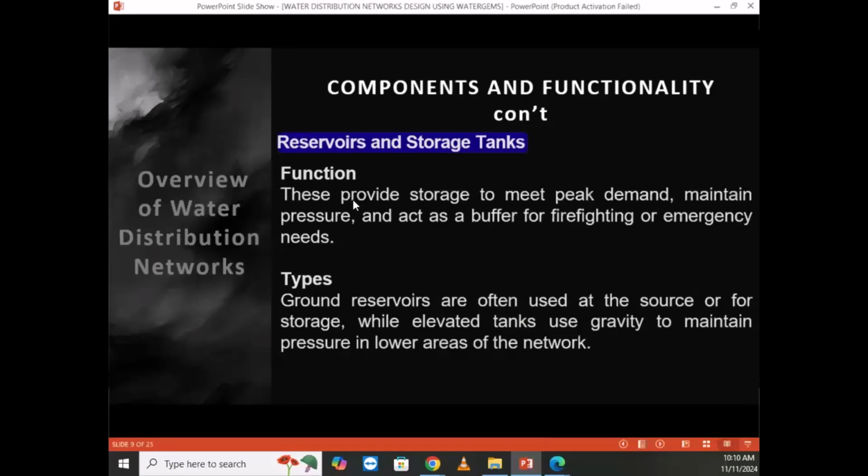So this also helps to meet the peak demand. All of us in the morning, people are consuming much water. If people are consuming much water in the morning, you have to size your tank so that in the morning the tank will be full, people will consume the water, and during the times of 10, 11, the water will be filling your tank. So that at 8 in the morning, there will not be an empty tank. That's a mistake that designers are making. You have to design your tank so that all day your tank will have water, without considering the peak demand or the lower demand.